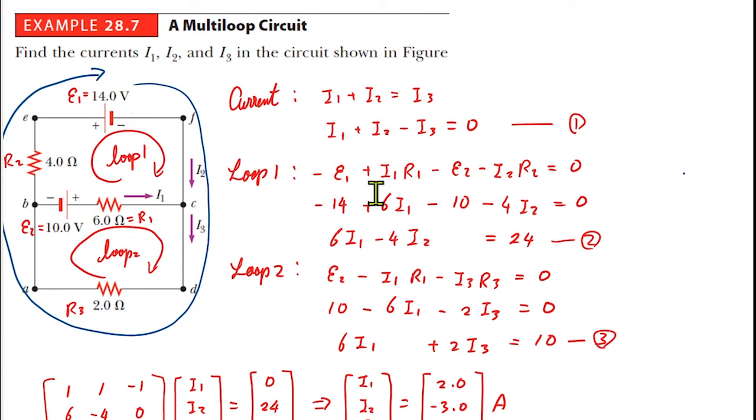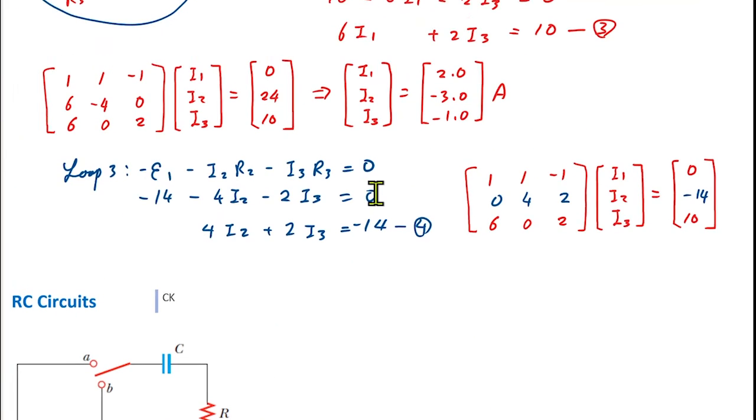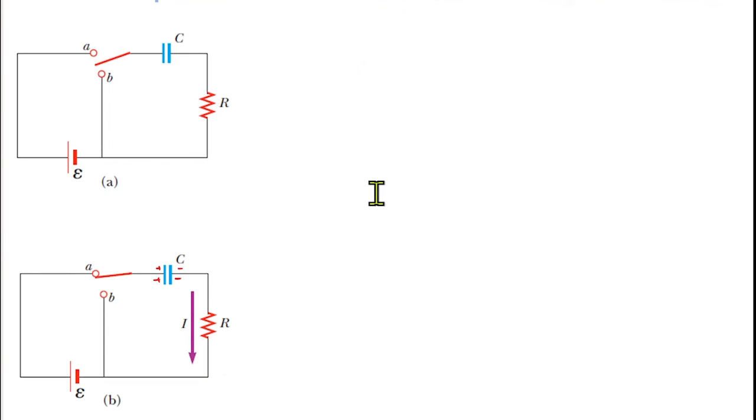Okay. In order to finish this in time, can we talk about RC circuit? This is a differential equation. So what happens if you mix the capacitor and resistor in the same circuit? Right now the switch is open on both sides, so there's nothing. So the current here is equal to 0 in this case. That's easy to see. But now we'll close the switch to the A side. So our current will flow in this direction.